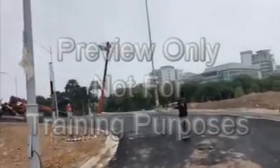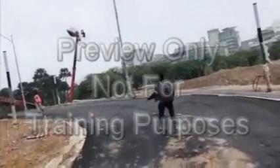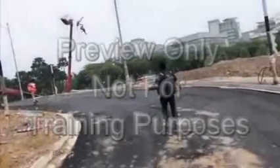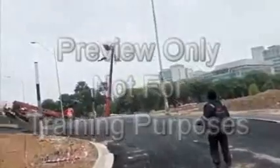Fall arrest systems are designed to stop a fall in progress. The arrest system must not allow an individual to strike any surface below the work area. A rescue plan must be in place that limits the amount of time an individual is suspended after a fall.